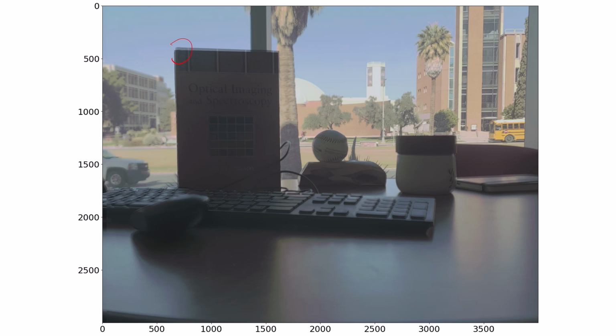But part of the idea of really the solution to this problem over time is to find ways to get multi-exposure images. Now, of course, today you can buy focal planes that can do raster scans of different exposure levels in different rows of the image, which will help a lot with HDR, but that only gives you two different exposure values, and really to get this kind of 8-order magnitude dynamic range, you need more sophisticated strategies.